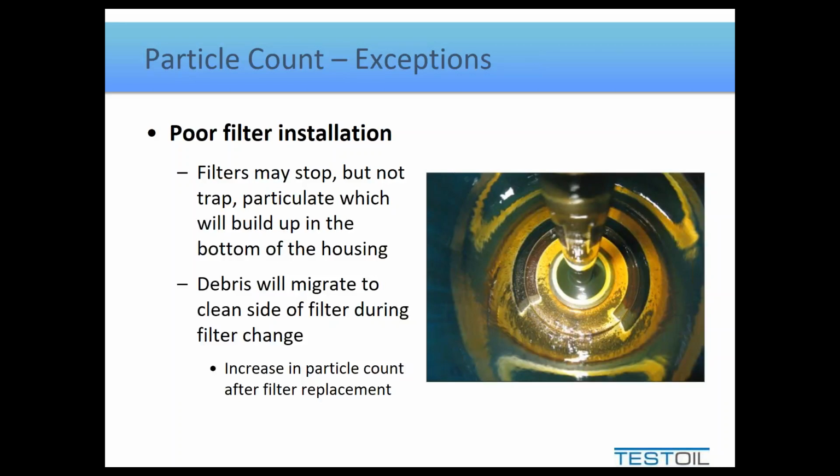So for this reason is why I like to point out that when we see the sawtooth pattern, we should really pay attention to what the particle count looks like both before and after the filter change. And if we see that the particle count continues to increase after a filter change, we should suggest cleaning of the housing and making sure that the seal is properly cleaned so that the new filter will, in fact, do its job properly.